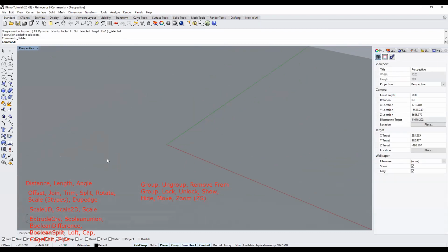Okay, so that's the end of interacting with objects. I'm going to get into how you translate a physical model into a digital model, but does anyone have any questions? Can you snap to a locked object? No. With locked objects, you can still see them, but you can't select them at all, so you won't be able to interact with them.